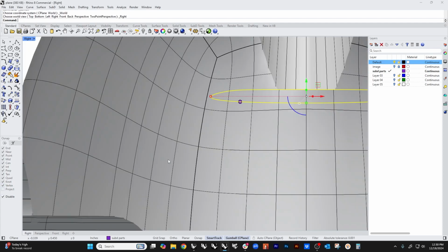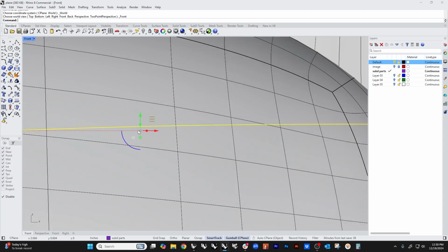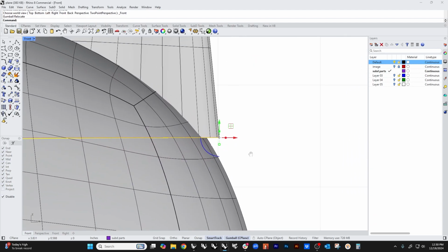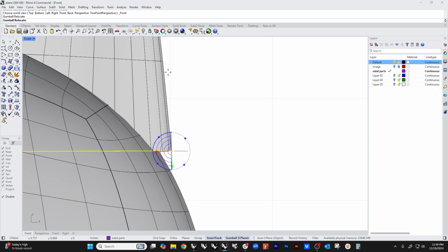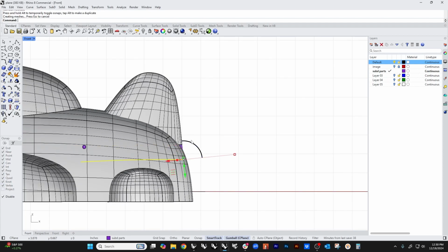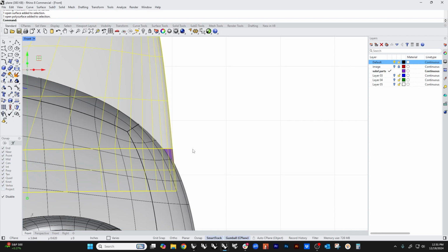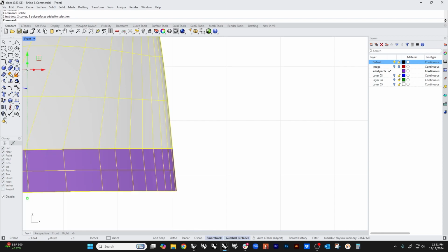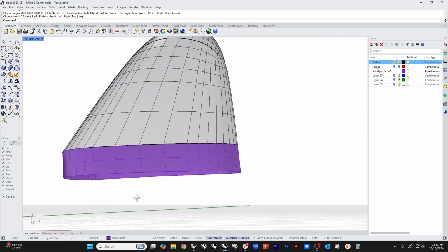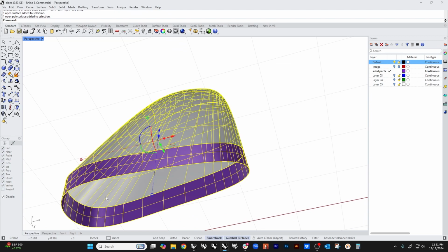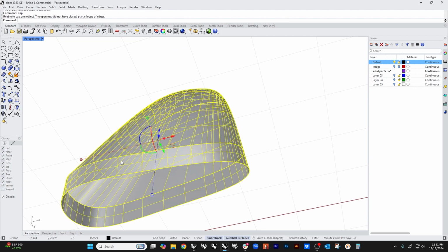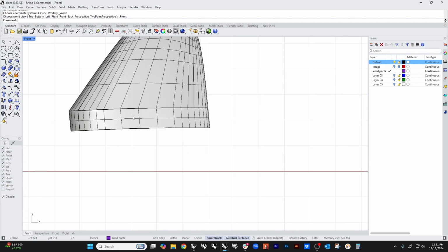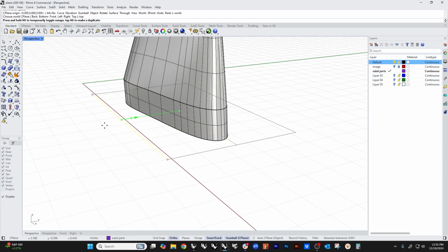We're going to go to the front view. And we're going to stick the gumball right there. And then I'm going to double click the rotation icon, and I'm going to snap it so that it's aligned right with the back. And now I can extrude that, and it's going to be more or less tangent to the back. It'll be tangent enough. So let's look at that, and we're going to combine this part and this part, and then we can cap it. And if it doesn't have a planar end on it, we can certainly just make one by just drawing a line through here. And then we can use the gumball cutter